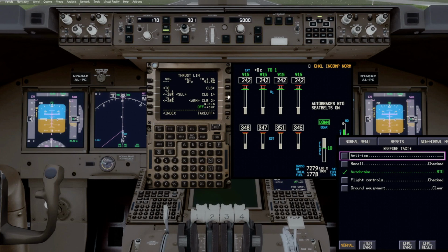You can change this thrust as appropriate. But whenever you select it, like TO2, it'll go to Climb 2. But again, if we don't want that, we can change it to Climb. You'll notice when we select TO2, the TO2 max N1 is now 87.4%. You notice the green solid lines, the hash marks have come down. They're at 87.4% now. The amber lines would represent that max N1 of 95% that we saw before.